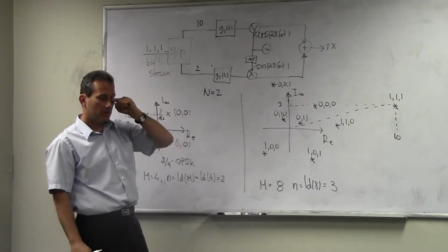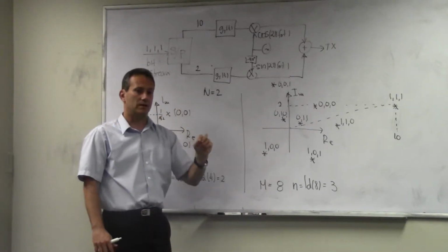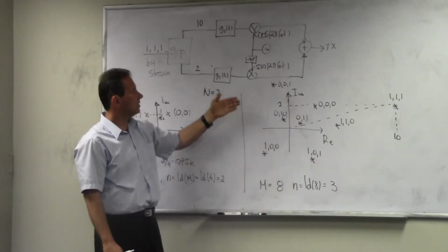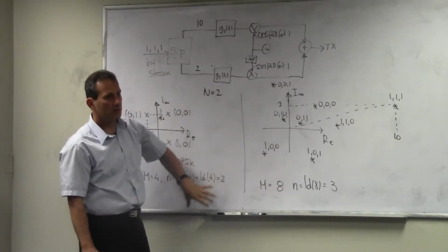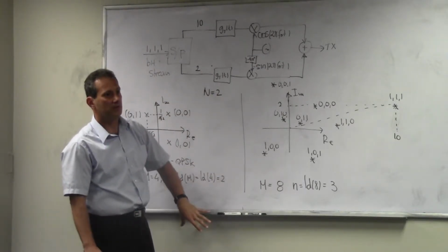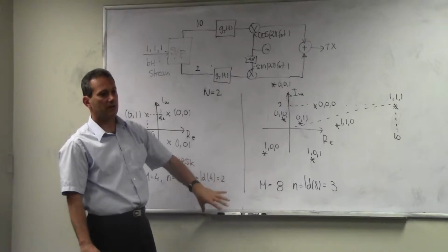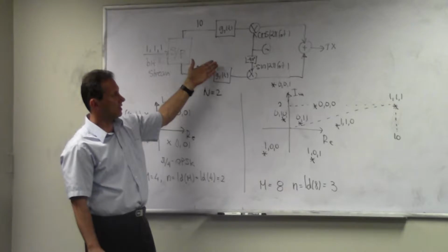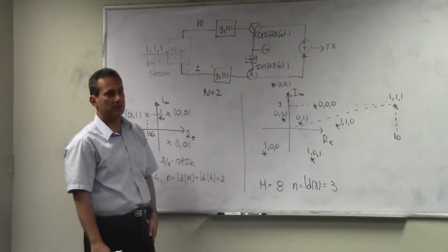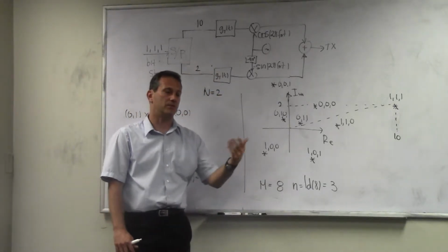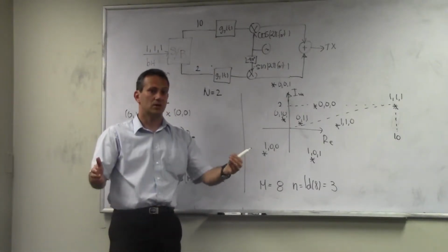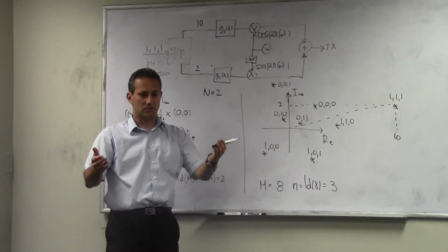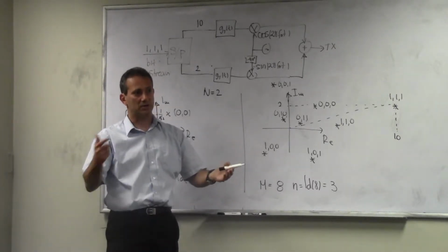But if you remember what I went over last time, the easiest and practical way we construct multi-dimensional space is we take this and then another one and another one and another one, all working at different frequencies. So you can see most practical multi-dimensional space as an aggregation of many two-dimensional spaces. If you use OFDM, and typically we quote the number of subcarriers, OFDM with 128 subcarriers would mean that this consists of 128 two-dimensional spaces.